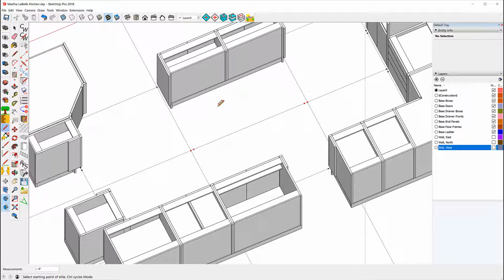and I think I want a 15-inch opening here. What we're going to have is a 3-drawer base bank here and a 3-drawer base bank here, each with 15-inch openings. So I'll use the distance tool, come out on the line, type 15 and enter.